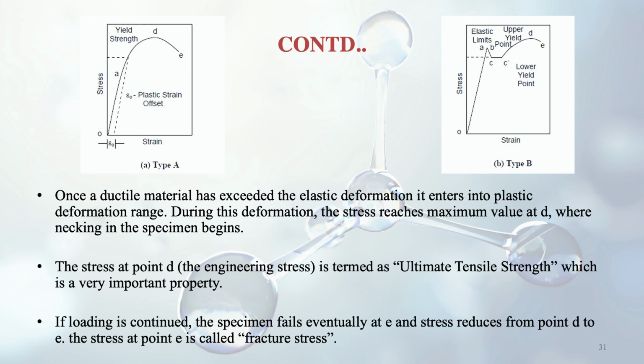But still it has not broken. Now the stress will come down. If loading is continued, the specimen fails eventually at E, and stress reduces from point D to E. The stress at point E is called the fracture stress. So the point E is the point of fracture.